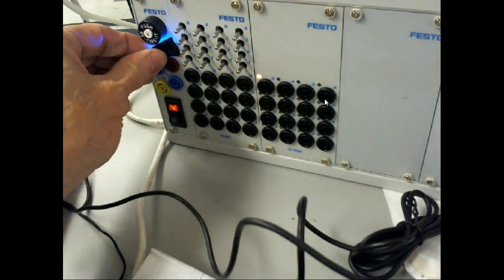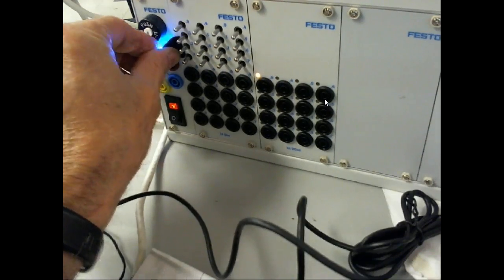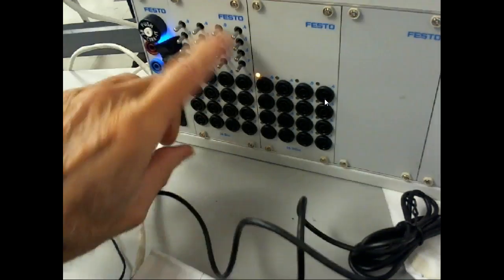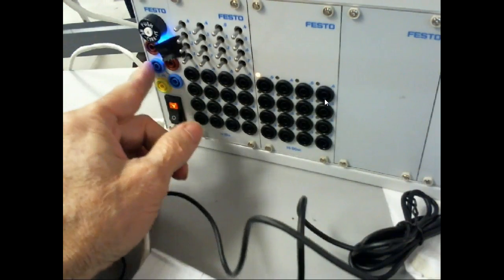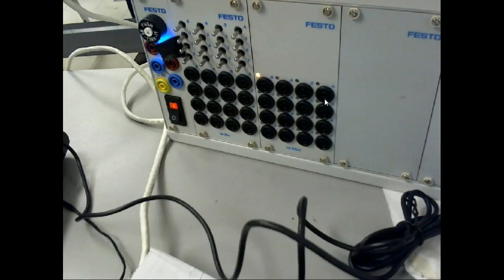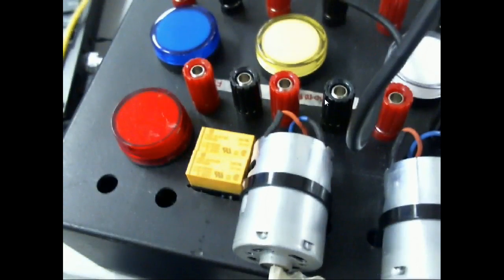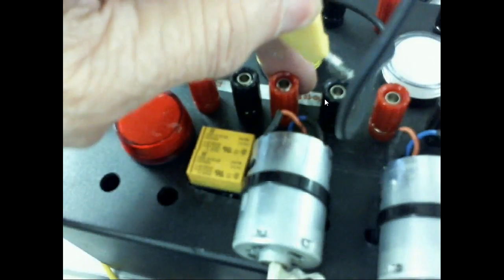Over in Germany, by the way, I deliberately taped that up because that's a really, really bright LED. So my output ports are sourcing, so I'm going to set up my device to sink, right? Understand? That means I'm going to take this negative right here, which is blue, and run it out to one of the commons of my motor. It won't hurt anything. With DC motors, the polarity that you hook up determines the direction. So right now we'll just go to black.